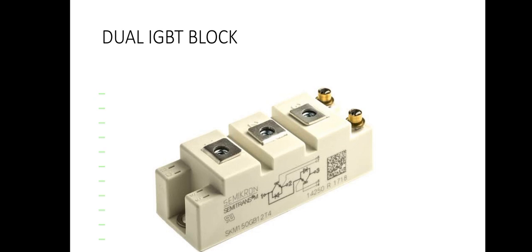And if, for example, you are using 6 MOSFETs for 7 kVA on each side, you can use 2 of this IGBT for 7 kVA for the 4 sides, because as you can see carefully, each block has dual MOSFETs in it. It is mounted on a heatsink and the fan has to be on standby. If you are using this kind of MOSFET or IGBT to design an inverter, the fan has to be on standby. But they are very reliable and very strong.